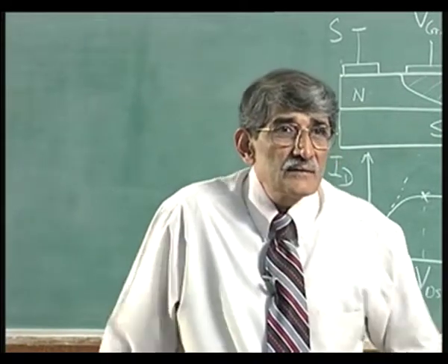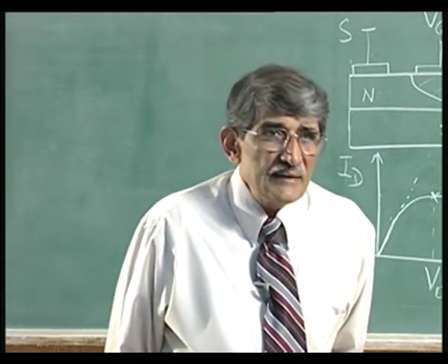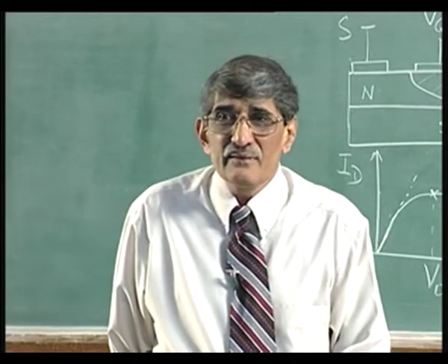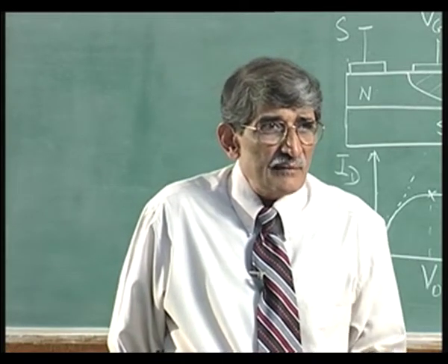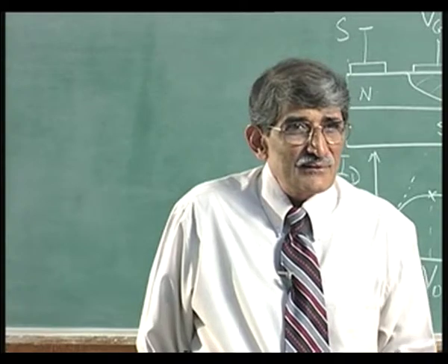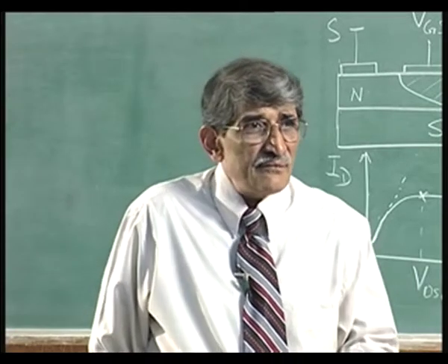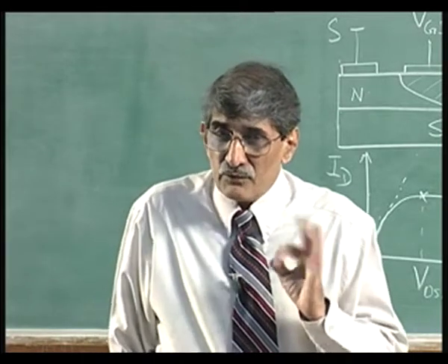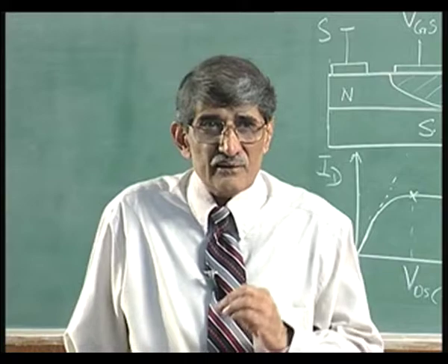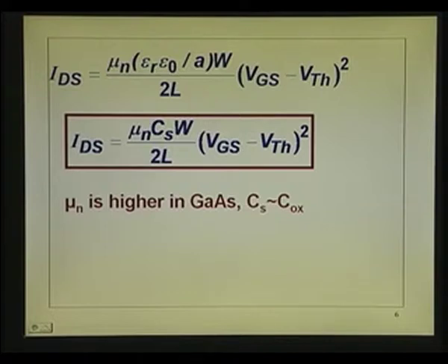If you take silicon, 1500 centimeter square per volt second is the mobility of electrons in the bulk. In the surface, due to scattering in the surface, what is the mobility? About 1000. People even worry about getting 1000. If you get 1000, your joy is quite high. You are very happy, because that is what you get. If a surface is rough, you will get 900, 800 of that order. So, it is not a device whose mobility depends on surface mobility, it is a device whose mobility depends on bulk mobility. So, even if you think of a silicon device itself, a MESFET, that would be better.